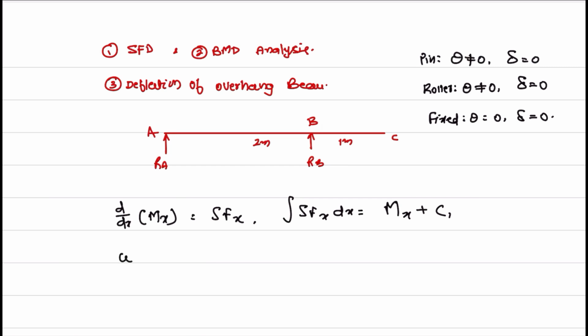Wherever shear force is equal to 0, that implies bending moment is maximum. That also we know. In this beam, shear force is 0 at 0.75, and at 0.75 we got the bending moment as 0.281. We have got these values and understood them in the shear force diagram and bending moment diagram.